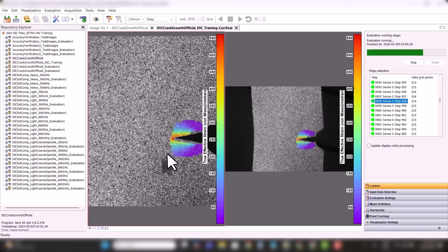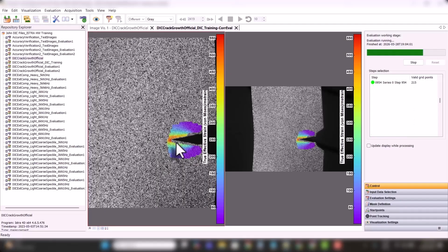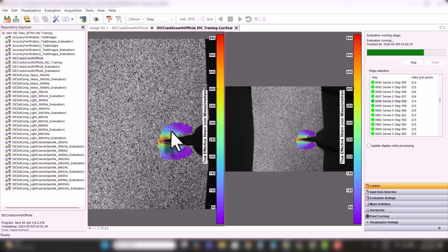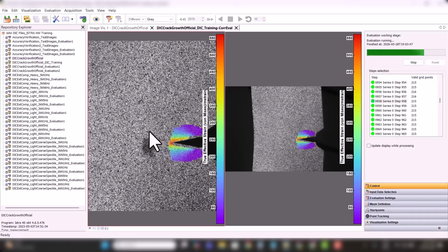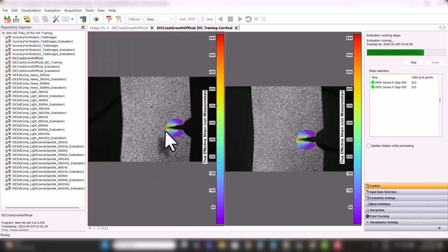So why does it seem to be getting worse as the crack gets longer, but for the main global correlation, that's not an issue at all? It must have something to do with the start points. It must be a lot more favorable, even for the local crack tip analysis, even the localized regions, to have start points just out here in the general field.